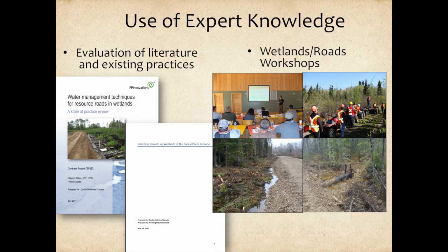But the real key thing, we did wetlands workshops where we did the Wetlands 101 training, and we worked with these companies ahead of time and asked them to take us to sites where they were having problems, as well as places where they were not having problems, so that we could really have a discussion about why you are having a problem with this particular crossing and why this one is working. Incidentally, the picture on the lower left, that road was built very, very shortly prior to our field visits, and already water was starting to pile up against the shoulder of the road.